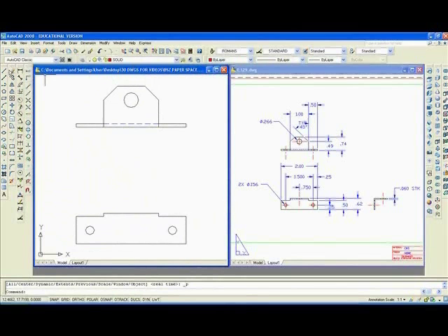And here I'm going to erase. And then I'm going to fillet, F-enter, and again. That piece will lay on top of the other. Then erase.